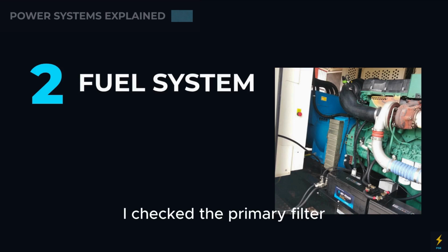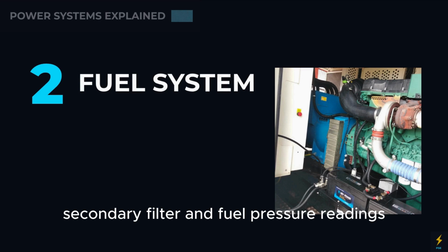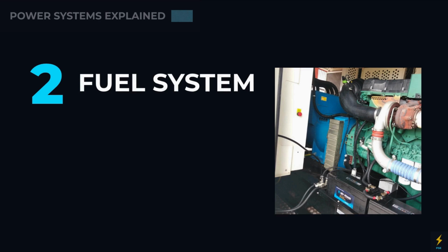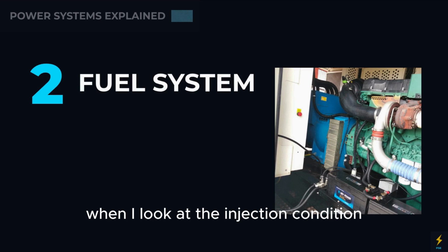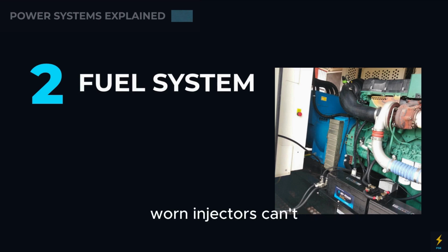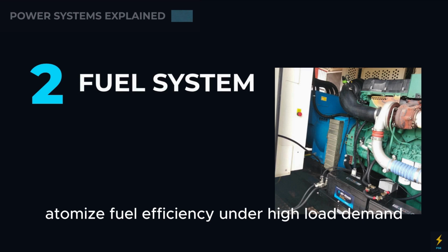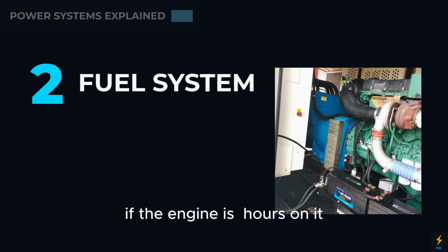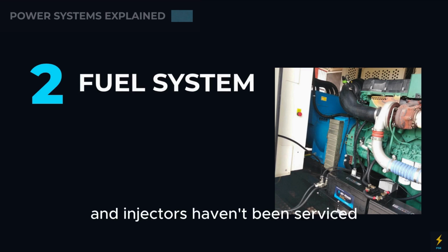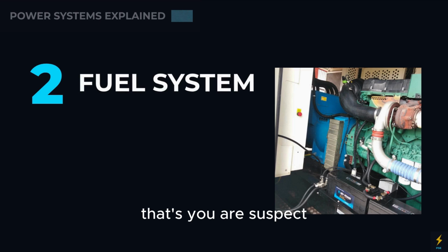I check the primary filter, secondary filter, and fuel pressure readings. When I look at the injector condition, worn injectors can't deliver enough fuel under high load demand. If the engine is high on hours and injectors haven't been serviced, that's your suspect.